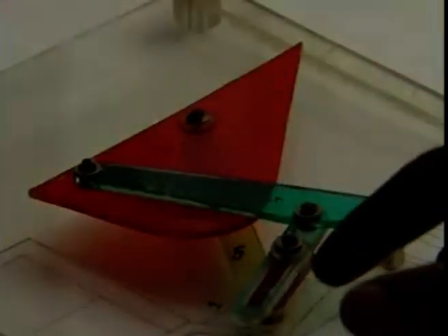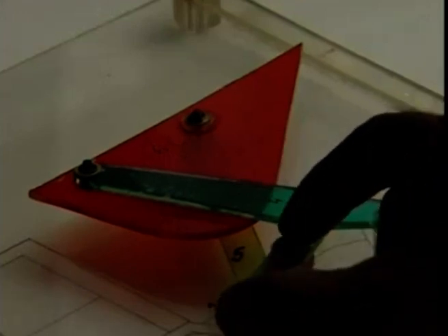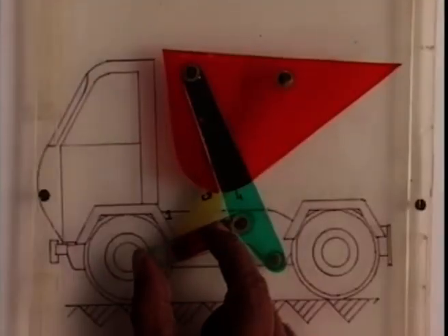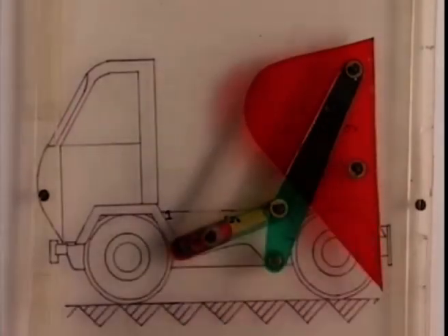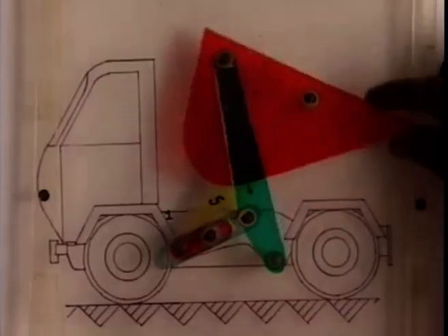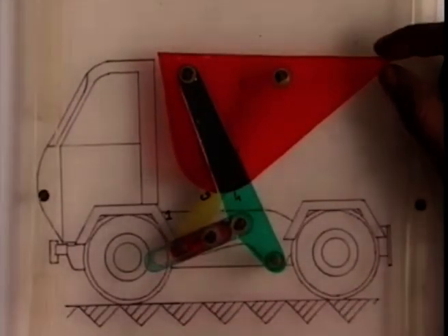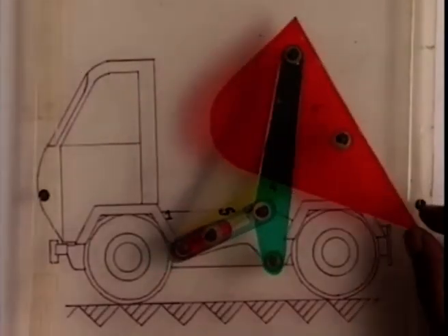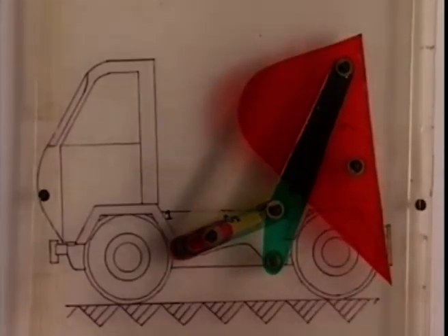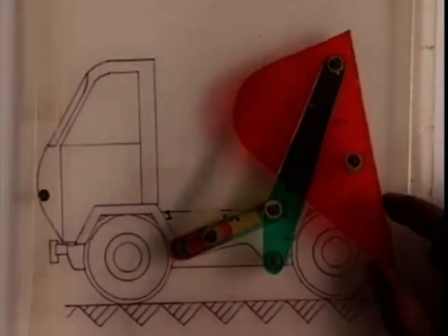This 4R linkage is driven by a hydraulic actuator such that link 4 is used as the input link and it is moved by this hydraulic actuator to move the dumping bin. This is again a guidance problem, in that I want to guide this particular coupler from this transport configuration to say this, then this, then this, and finally to the dumping configuration. So this is again a motion generation problem without any coordination with the input movement.